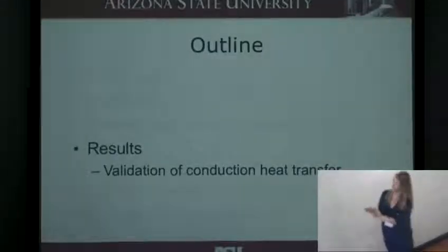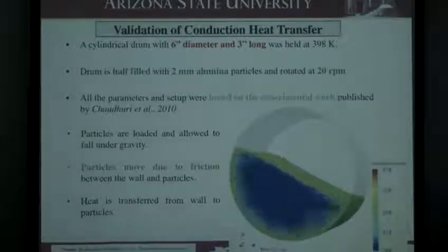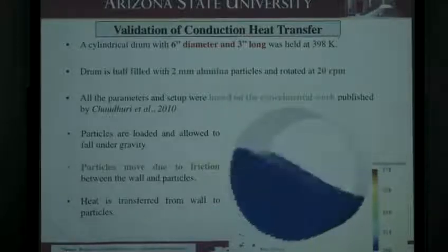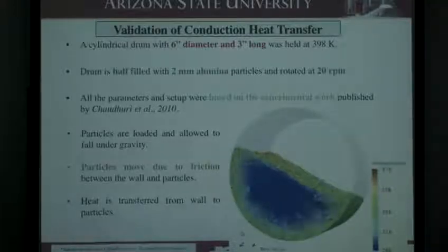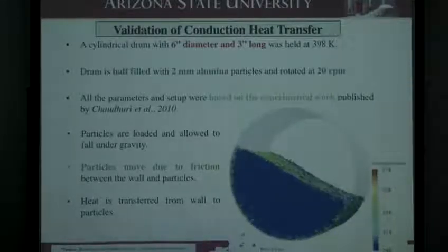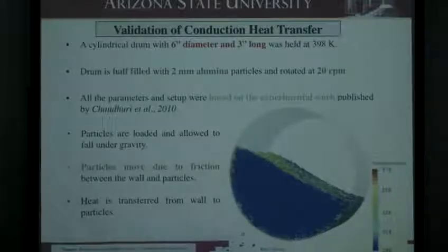Okay, so the first set of results is validating conduction heat transfer, and it was really difficult to find experimental data in the literature. We found one paper that we were able to extract data from, so we just tried to replicate those experiments with these simulations. These are MFIX simulations. It's 50% fill, because that's what the paper did, 6-inch diameter, 3-inch long, with 2 millimeter diameter alumina particles, and the rotation rate here is 20 RPM. And here we have the heat transfer from the wall to the particle bed.